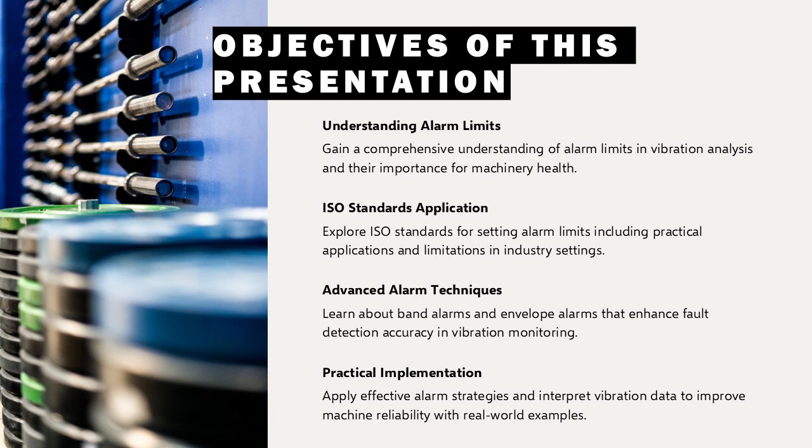We will explore the ISO standards for setting alarms, including their practical application and inherent limitations. Additionally, we will delve into advanced alarm techniques such as band alarms and envelope alarms, which offer more precise fault detection capabilities. By the end of this session, participants will be equipped with the knowledge to implement effective alarm strategies, interpret vibration data accurately, and apply best practices to enhance machine reliability. Real-world examples and diagrams will be included to illustrate key concepts and ensure practical relevance.